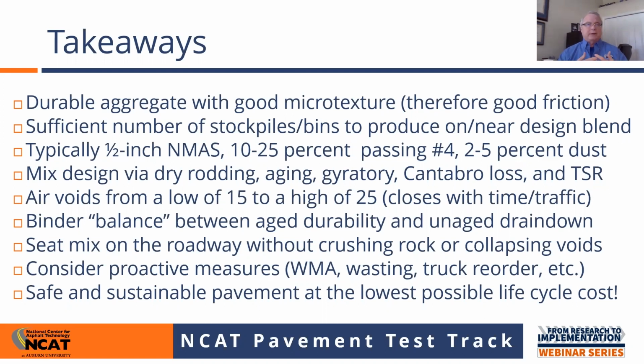But I know from my experiences with FDOT, we would have a lot of projects that, maybe 4, 5, 6 years into it, you'd have isolated areas with raveling. And I really think it gets back to having the mix temperature. And Buzz, the thing you pointed out about transverse joints, it was something Buzz pointed out to me about a year or so ago. You start driving through projects and you realize there's a transverse joint, and then you've got raveling for about 100 feet and it goes away. And then next time you hit a transverse joint, the same thing.